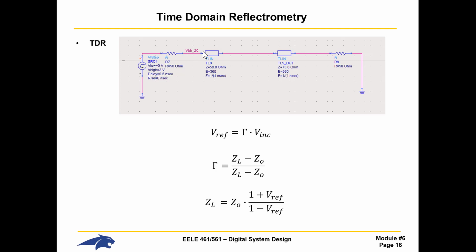Maybe it's like 100, 200 picoseconds, a couple inches between where the source impedance was and the actual connector. So you always have some sort of transmission line that sits after the 50 ohm output impedance. And that's why you put it here. Then if you added like a cable that was a nanosecond, you just change the delay of this transmission line.